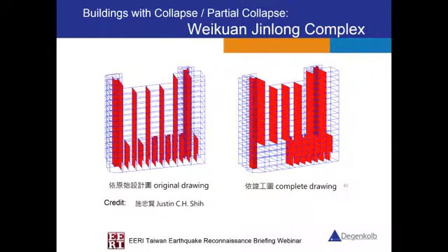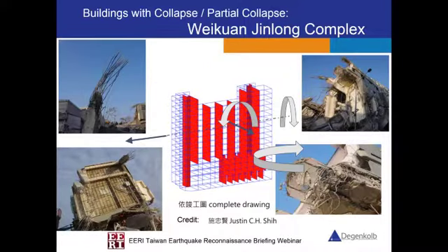If you look at the model shown in this slide, the left-hand side represents the original drawings. If you look at the bottom left corner, you'll see some structural walls below the fourth story. But on the right-hand side, which is the as-built drawing, you couldn't see those walls. From the pictures actually taken after the earthquake, before they completely demolished those buildings, we can see that at the tension side, you'll see the rebar failure, either necking or rebar coupler failure. In this structure, we think it is a combination of vertical and plane irregularity, torsion effect, and lack of system redundancy that caused this collapse.